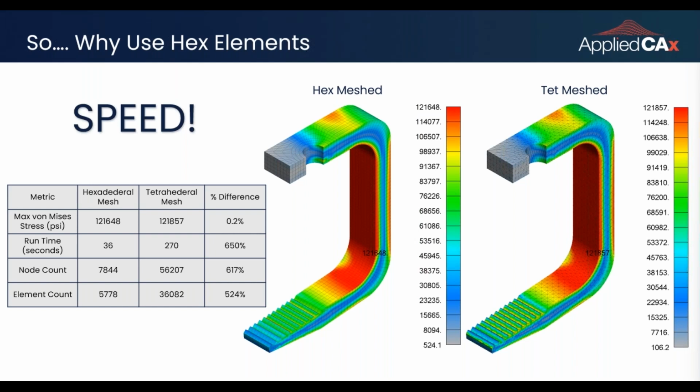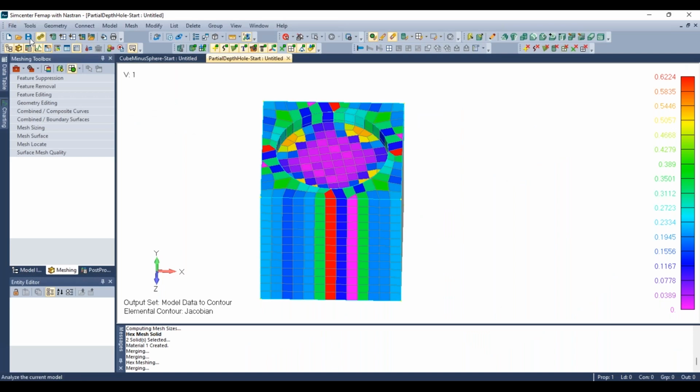And again, you haven't really improved your accuracy by doing so. So adding that, changing all of the elements to parabolic and using the automatic hex mesh generator, they kind of fight each other a little bit. I see we have a few minutes left. Maybe let's pull up one of your two-hole examples, what the auto hex mesher does to it. Yeah, that's a good idea.